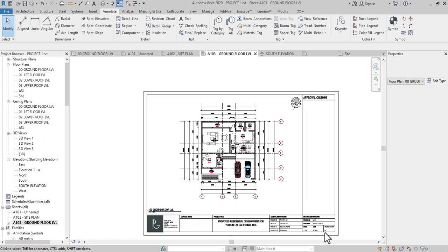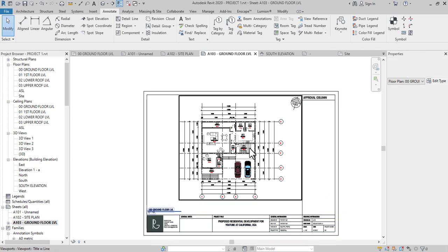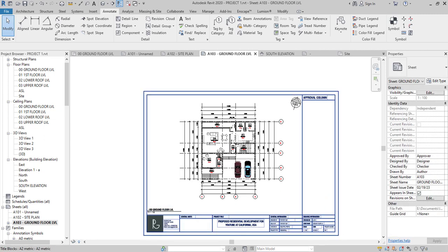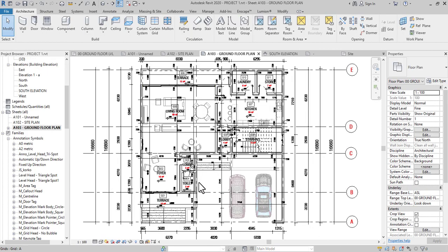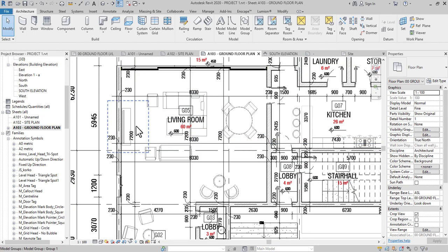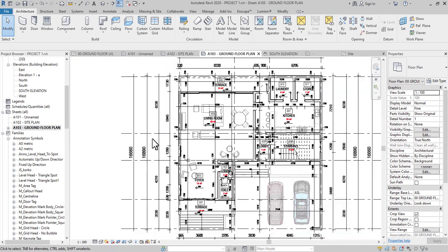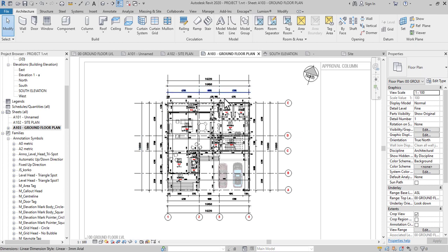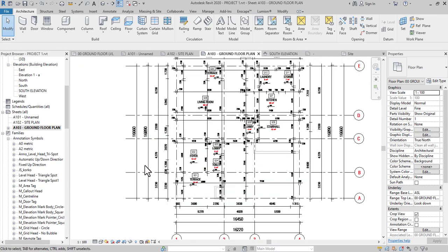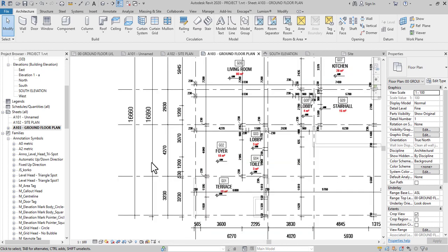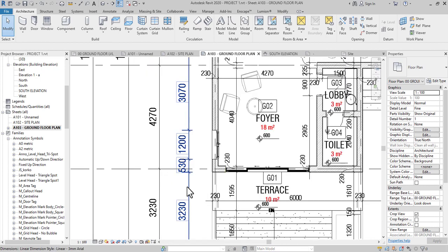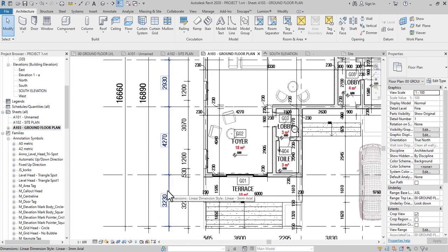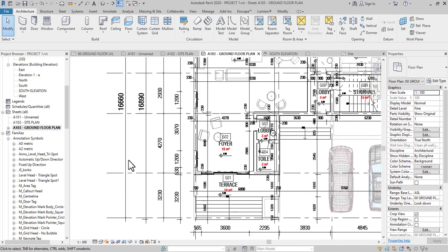So I've done most of the work now, and as you can see, dimensions on the exterior and interior. So let's go over some of the fundamentals. If you notice, this text and this text, the font size is the same. This is slightly bigger because it's the overall. So I use it like this, a step higher. So if this is 3, this is 4. Same all around. So the grid, overall grid and overall building is the same text.